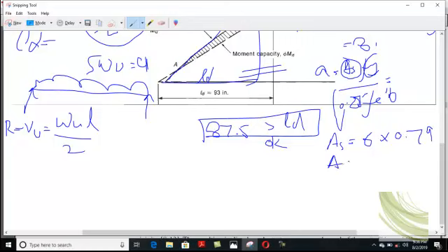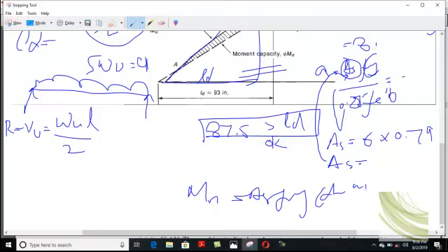So you will get As. Putting that As in, everything else is the same, you will get the A value and then again put that value in the Mn equation. Clear? A is Fy into D minus A over 2. The value which you get from this, you put here, and Fy is the same, you will get Mn.